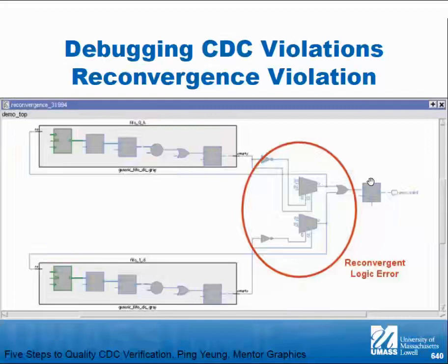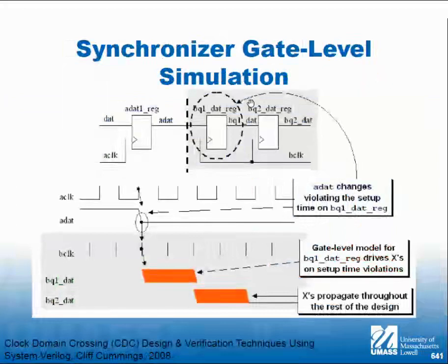Bad idea, right? Define your clock domains clearly. No logic in between. If there's no logic in between, it has to be one clock domain to the other anyway. Can't have, because the logic is what we're combining.